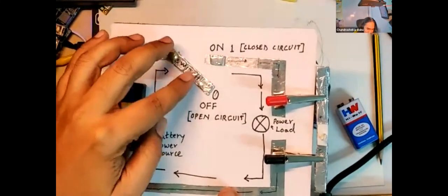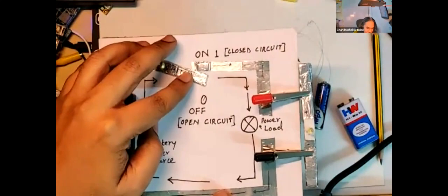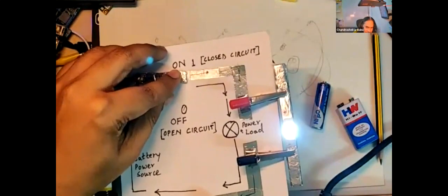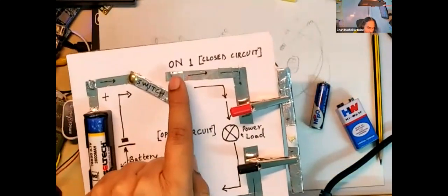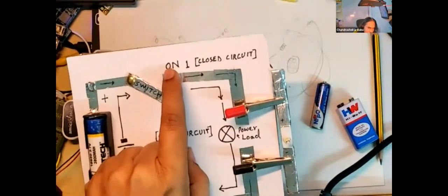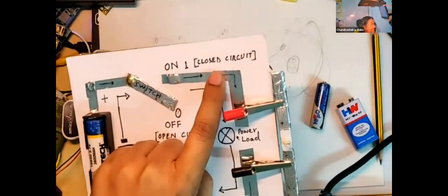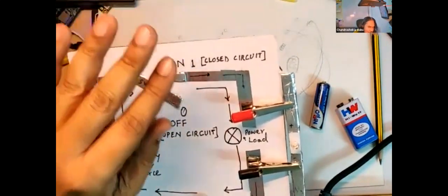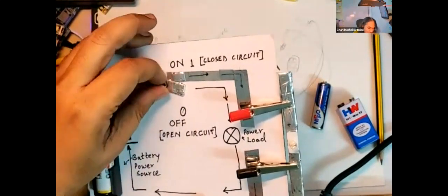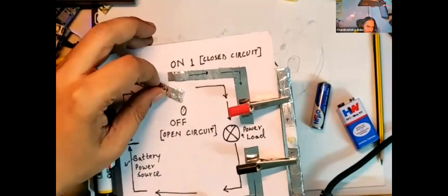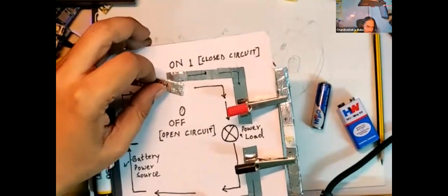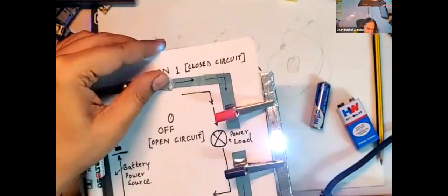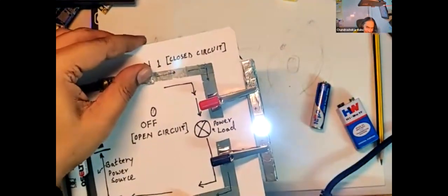But what happened was, I tried to create a switch here. This used to turn on the moment I put this in here, but now it's not turning on. So it's flickering. Do you see that? You know why it's flickering? There's a thin layer of oxidation that happened on this aluminum. And this oxidation can create what we call insulation and loose contacts, because it's actually acting as an insulator now. Though these two are metals, when I touch it here, nothing happens. It's not conducting, right? I have to put it on top, press it and scratch it like this, and then the light sort of flickers.